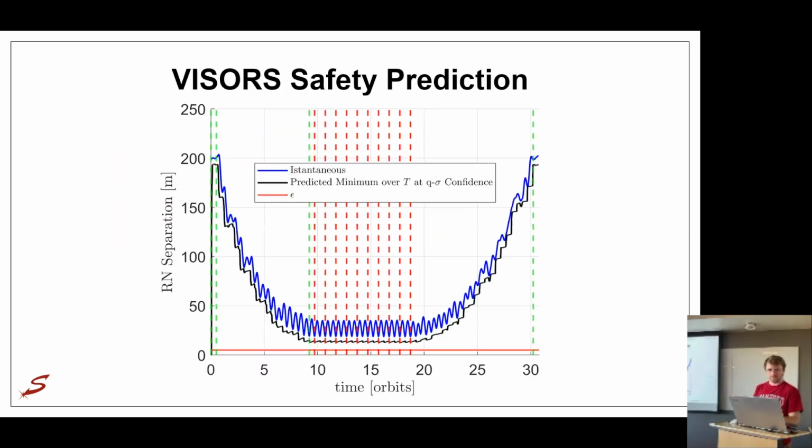And so during the nominal operation of the VISORS formation, this happens separately in the RN and the RT planes. The RN is checked first because it is supposed to be stable and lower uncertainty. In the RT plane, you do have elongation, particularly along the T direction of the uncertainty ellipse.